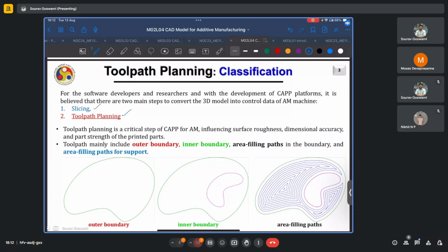Say an optimized orientation in which you can minimize the supports. It will also, of course, generate the supports by itself. It will highlight the areas which might require supports. Of course, you are free to switch them off should you think they are not needed. But the point here being that these software packages abstract out a lot of these processes that are working in the background.